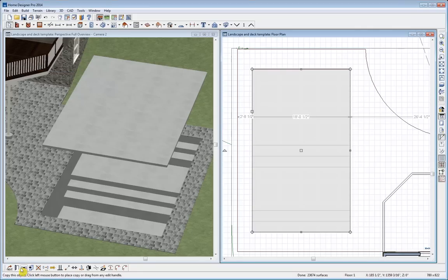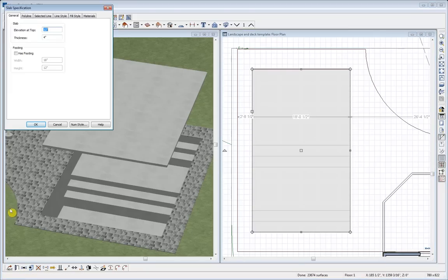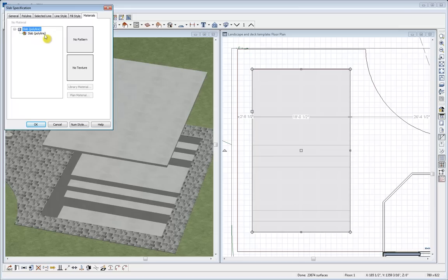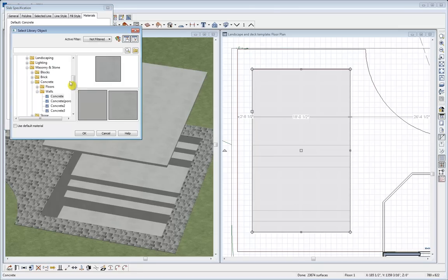And we need to open it up, change it to negative 4 inches so it sits just below the terrain so it's not going to overflow. And then we'll change the thickness to 76 inches thick since it's going to cover the entire pool. And then we'll also need to change our material from a concrete slab, get into our library.